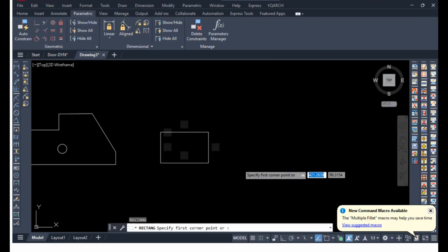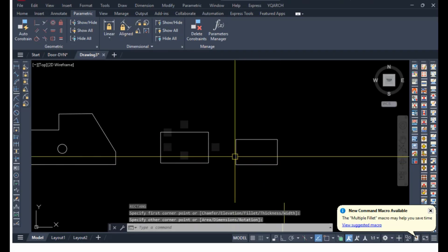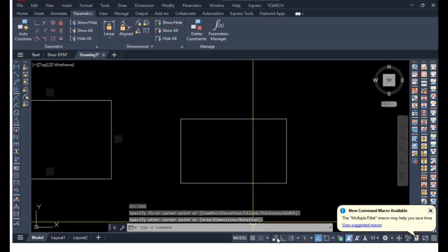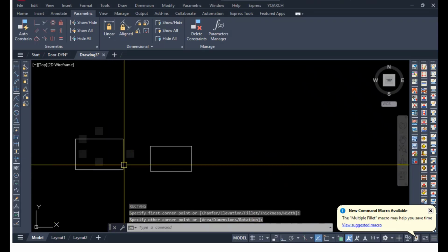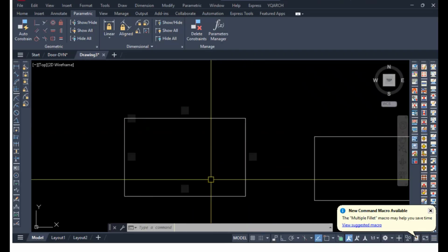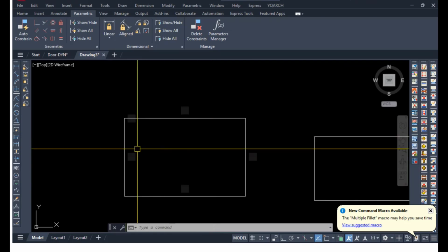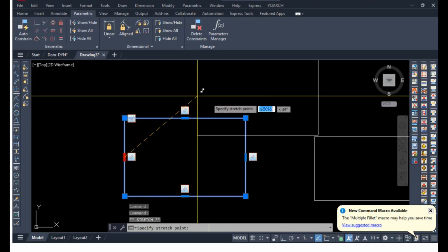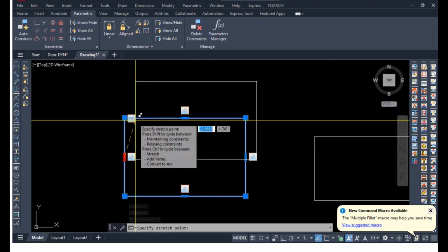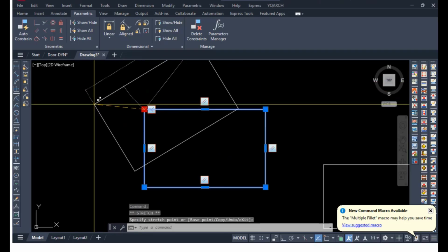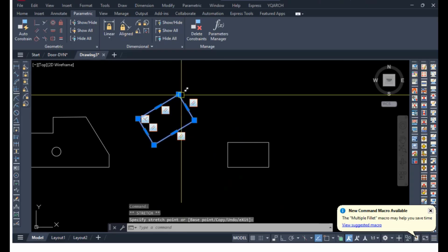When you draw the rectangle, nothing is constrained. So infer constraint means automatically applying the constraints on the shape that you decide. And what's the benefit? You see, this rectangle has constraints on it. When you move anything, it moves while maintaining the shape of the rectangle. You can't change the shape of the rectangle. It's still a rectangle all the time.